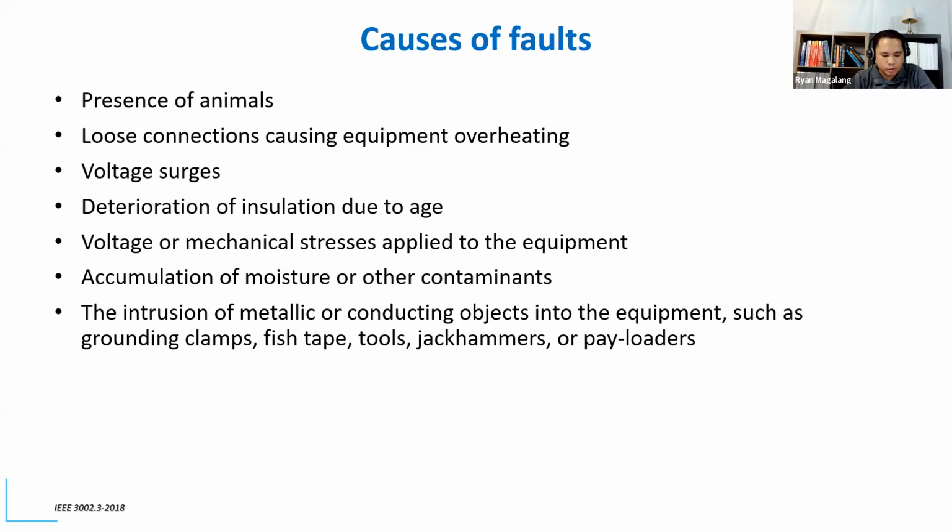Those are forms of insulation that over time would deteriorate due to age. Voltage or mechanical stresses, so overvoltages would also cause damage to insulation and would eventually degrade the insulation that could cause faults.